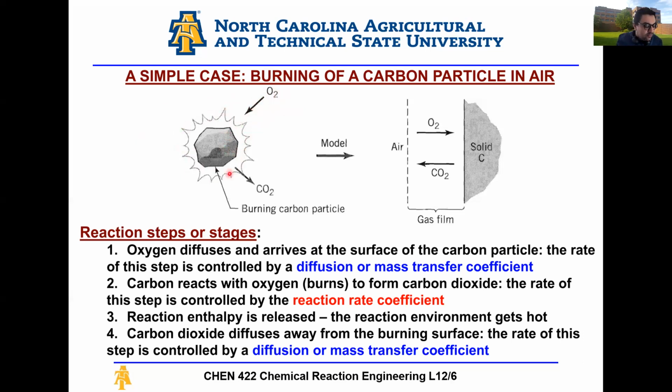On the other hand, if the mass transfer occurs very quickly and your reaction is actually extremely slow, then in this case, you need to design your reactor in a way so that the reaction proceeds faster. Maybe you want to have interstage heating if it's endothermic. Maybe you have a lot of cooling internals if it's exothermic, just to drive this reaction forward, because this is really your rate limiting step in your overall process.